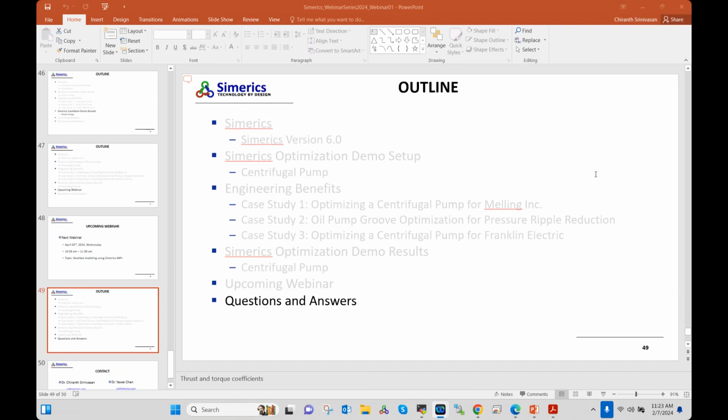From Hannah Boland, in the constant gas model, there is no transport equation solved for the air, gas or air going in and out of solution. The gas mass fraction is fixed and always free, but the volume fraction varies. It basically simulates small bubbles that are always present in the fluid and never dissolve. Yes, Hannah is essentially helping us answer Sheetal's question, so that's fantastic.